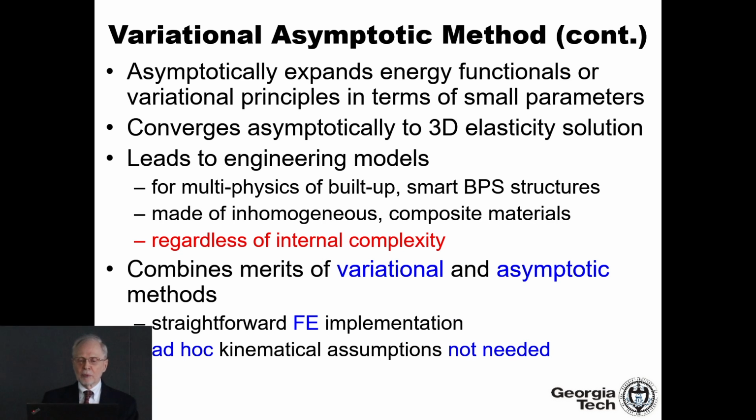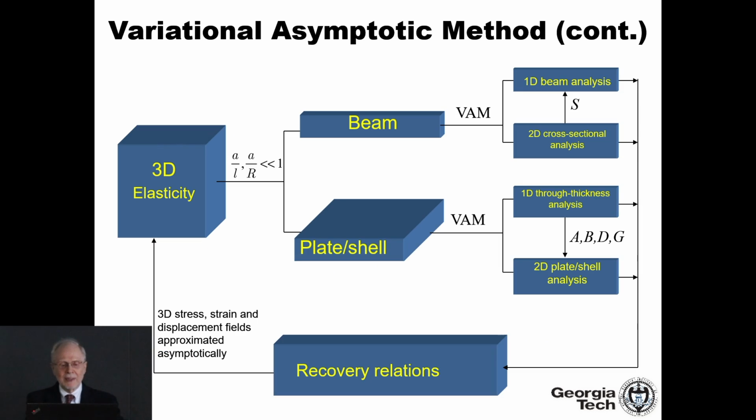This method asymptotically expands energy functionals or variational principles in terms of small parameters. It converges asymptotically to 3D elasticity solutions and leads to engineering models for multiphysics built-up smart structures made of inhomogeneous composite materials regardless of internal complexity. It combines the merits of variational and asymptotic methods.